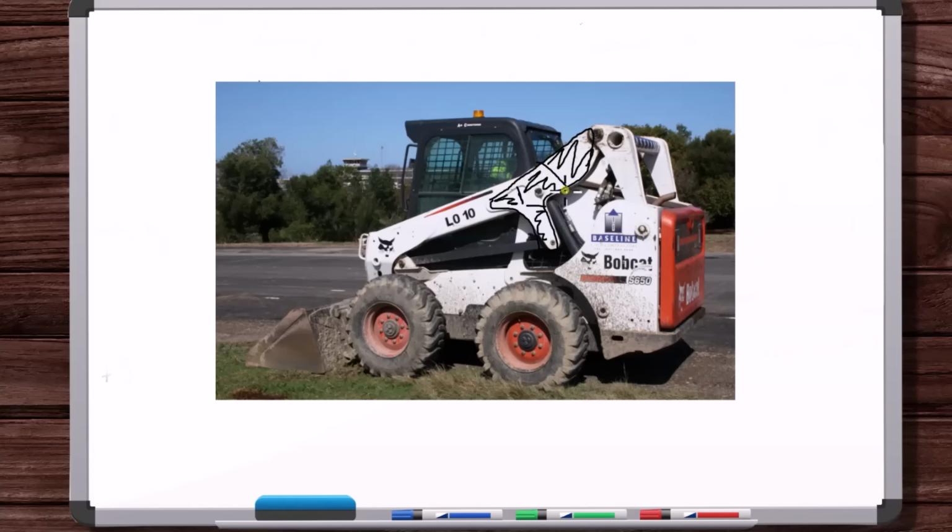Or if this was made of rubber, if you had the middle part made of rubber, but everything else was made of metal. Well, if all of the load is going through the rubber, and everything else was steel and you had these full loads on here that the steel would carry, because all that load has to travel through a pure cross-section of rubber, the whole thing would deform, right? So all of these forces on the steel would change their orientation, so it's not a rigid body anymore.